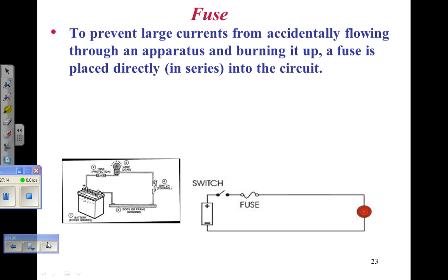Okay, let's go much higher. Let's go 150%. So we're going up the exponential curve. At 150%, at 30 amps, how long will it take to kick off? A fairly short period of time. Okay? Now, let's go up even higher. We'll go up to 200% now, which is only a little higher on the exponential curve. Now it will kick off in about a quarter of a wave.